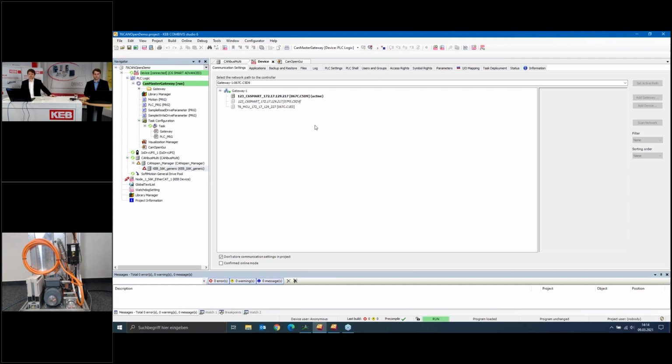And if I start this project now, you can see that these nodes here are getting green. This basically indicates that my CANopen master, which is a little industrial controller that is here on the bottom, you can't see it, but I guess you can trust me in this. So there's a little CANopen master connected to the same CAN bus like my laptop and the CANoe, and is firing up a CANopen slave, which is visible over here. And as it is already indicating green, it basically shows communication is active and communication is done.